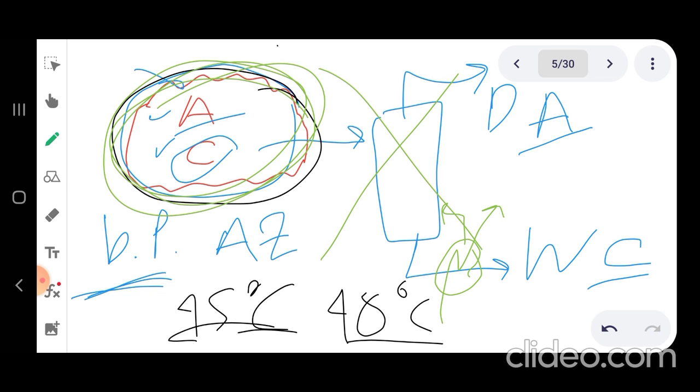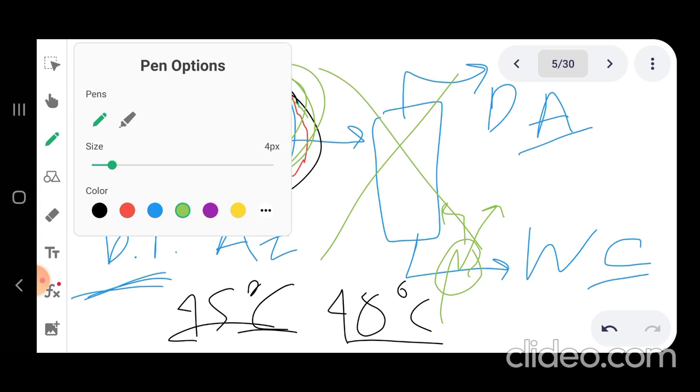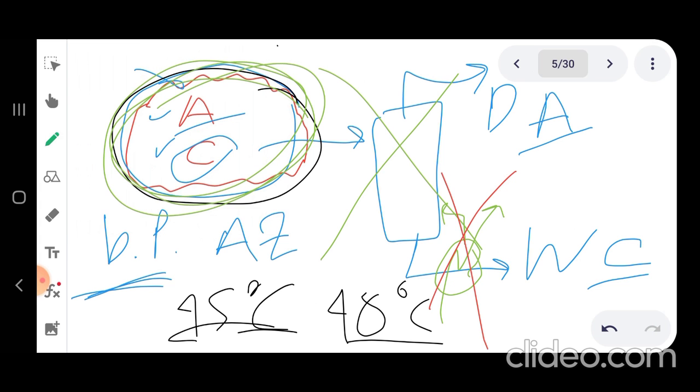One of these alternatives that we can go for is extraction, especially if you have liquid phases, liquid extraction. So again, it begs the question, what's the meaning of extraction? As you might think, the first thing that may come to your mind is that in extraction we don't need a reboiler. Why? Because sometimes we avoid distillation because of this reboiler that has a high temperature that initiates other chemical reactions.